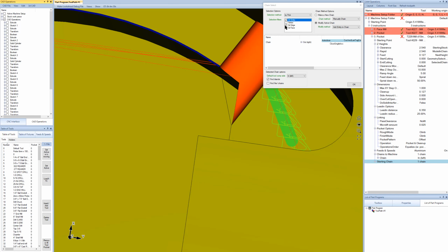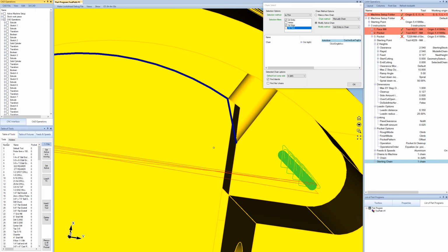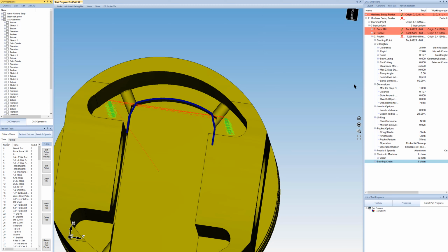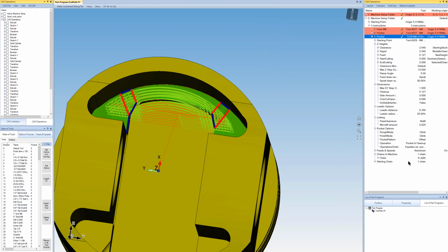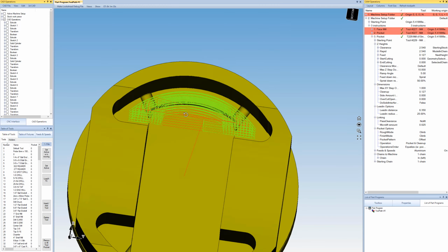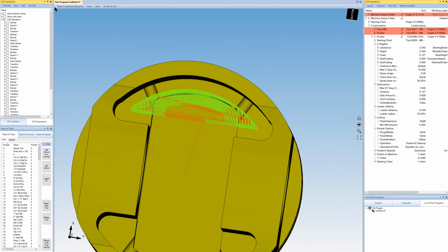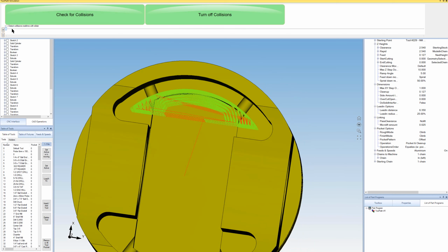Let's turn off the 3D face here. That should make it a lot. Yeah, there we go. That's going to help a lot. Okay, so this last one here. So now this tells us basically where the tool is going to start feeding in from. So now we'll go ahead and compile that, and that's kind of what we're looking for. All right, nice, smooth, flowing toolpath, and you can see it's going to start from the inside and work its way out to the perimeter. Okay, so that's good.